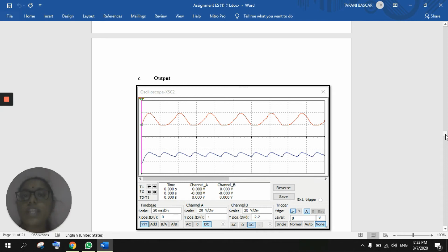So why does the capacitor have to release energy? Because when the capacitor releases the energy while the voltage is decreasing, it prevents the circuit voltage from dropping too low. And once the voltage rises again, the capacitor is going to absorb the energy again from the circuit, so that it prevents the voltage from rising too quickly.